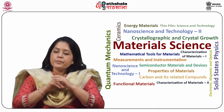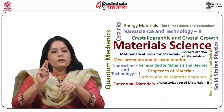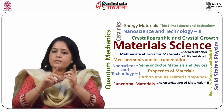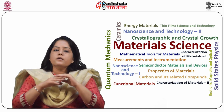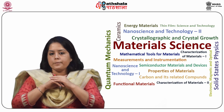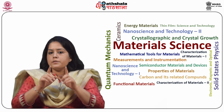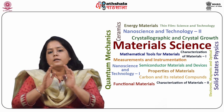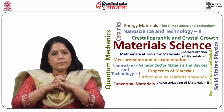Thirdly, the shape memory alloys exist in two different states, that is, austenite phase at higher temperature and martensite phase at lower temperature. Fourth, there are two types of shape memory effect, that is, one-way and two-way shape memory effect, which have been discussed.